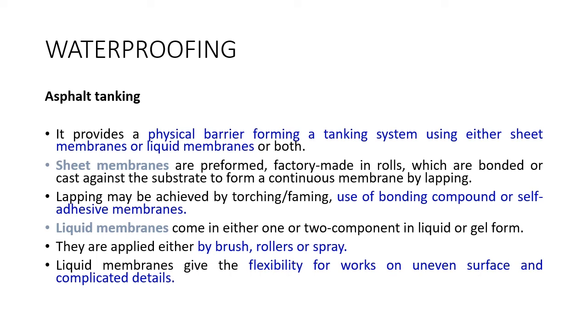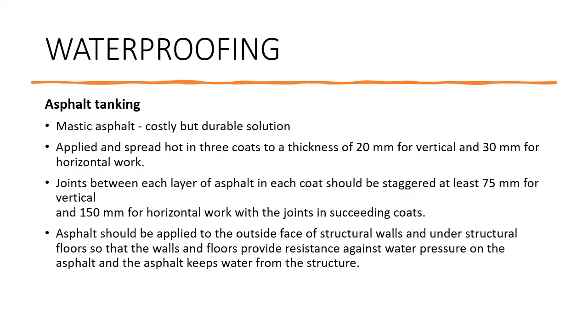Liquid membranes come in either one or two components of liquid or gel form. They are applied either by brush, roller ataupun spray. Liquid membranes give the flexibility for works on uneven surface and complicated details. This method is costly but durable.